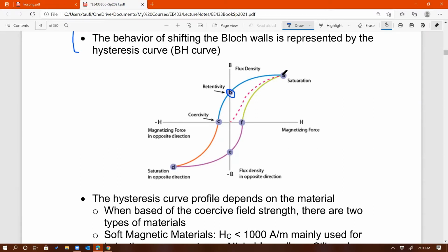And then when we apply negative current, or not negative current, sorry, negative voltage, meaning discharging the component, even if the field is no longer there, you see that when H is equal to zero, we still have some flux remaining in the core, right? And it takes more energy to reset the core to zero flux, as you can see there. It takes negative current to reset the core to zero flux. So that part we talked about last time.